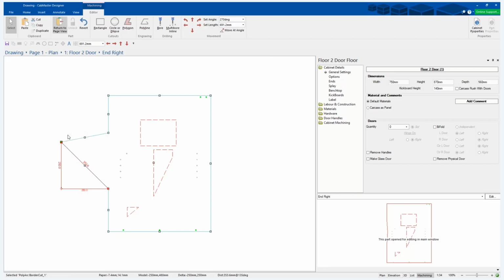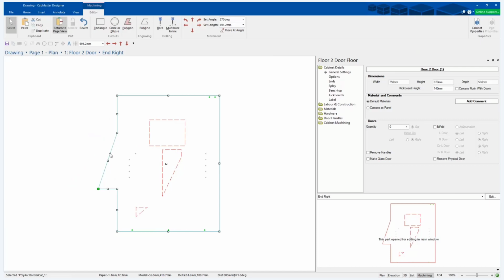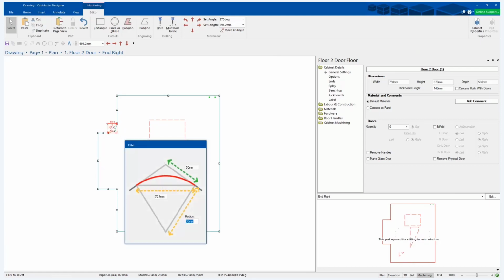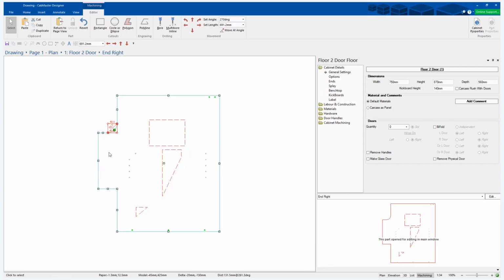And you should actually be able to, there you go, you can press the numbers 1, 2, 3, 4, 5 and it gives you an actual length. So I'm 100 mil out to there, and I'm going to go and add another corner here and go add corner and press 1 again, 100 mil up. Okay. So I'll go to there. So I've now done this. I can now go fillet corner. So there's a lot of things you can actually do in here.